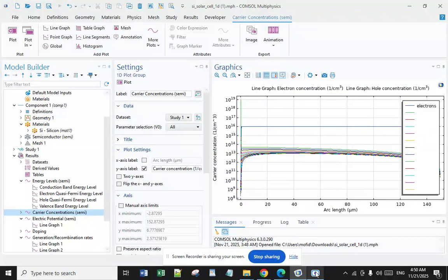And what about the perovskite photovoltaic? Perovskite solar cells are a type of thin film cell and are named after their characteristic crystal structure. Perovskite cells are built with layers of material that are printed, coated, or vacuum deposited onto an underlying support layer known as substrate. They are typically easy to assemble and can reach efficiencies similar to crystalline silicon in the lab.